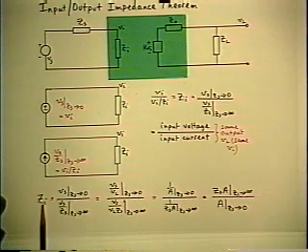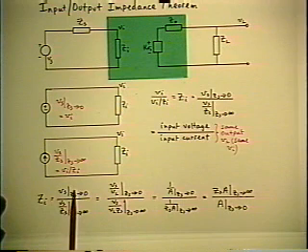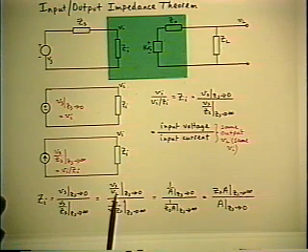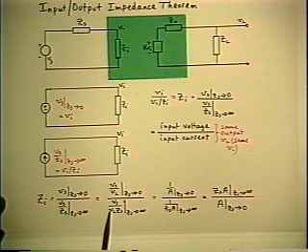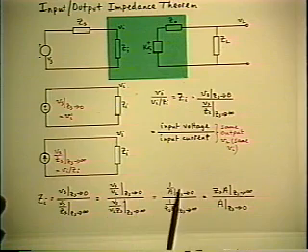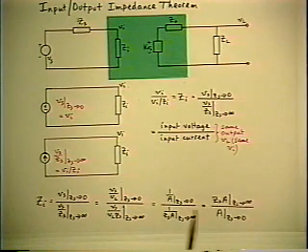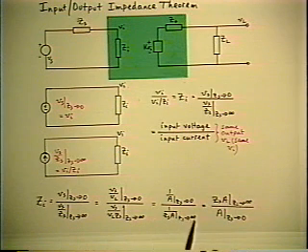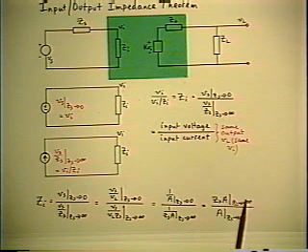So here's the starting point. The input impedance is the input voltage divided by the input current. To get the same VL, I divide VL into both of them. And now, once again, I can recognize VL over Vs in two places, which is the original voltage gain we already know. You just get rid of the internal fraction and bring this one up to the top, and that's the answer.